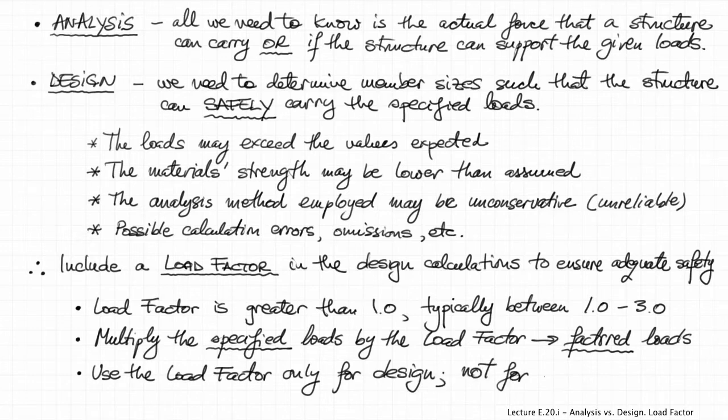For analysis, where we just check the adequacy of a structure, we don't need this extra safety. We just want to see a number, exactly how much force that structure can carry. So therefore, the load factor is always used for design problems, but is not typically used for analysis problems. Very important to remember that. When to use the load factor? Only for design, in general, not for analysis.